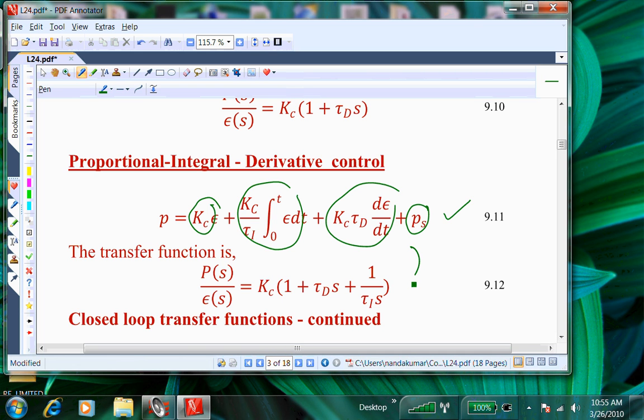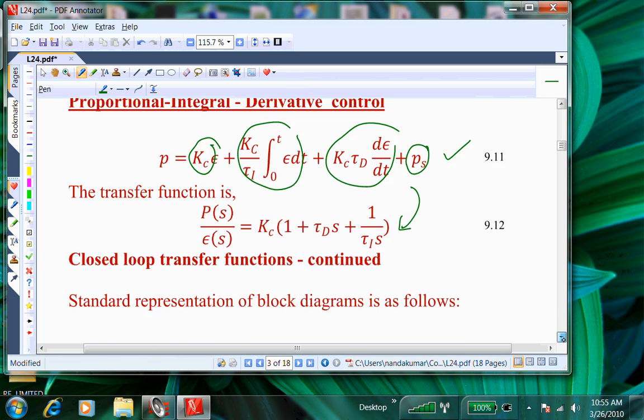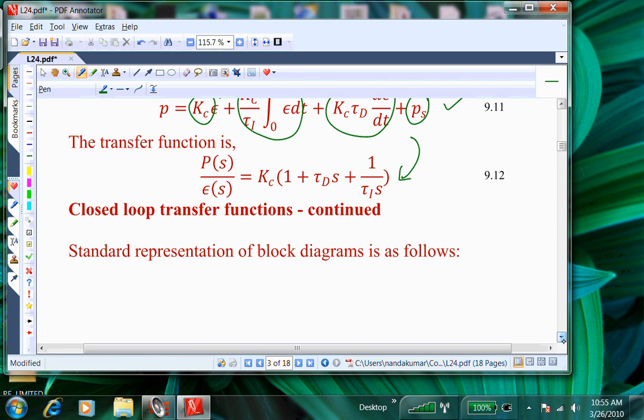And its transfer function is given by simply taking the Laplace transform of that, and there are 3 parameters that we need to tune. And we are seeing that Simulink gives us a built-in module for implementing that particular transfer function, which is a PID controller.